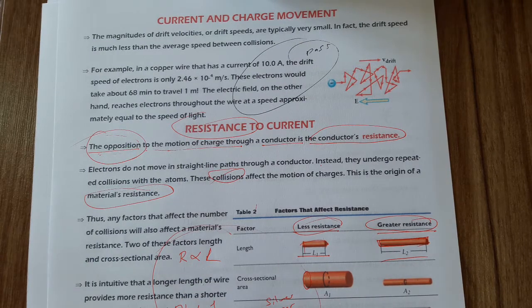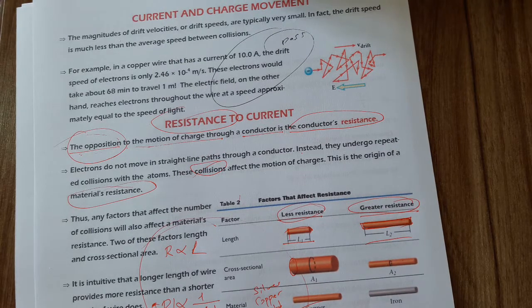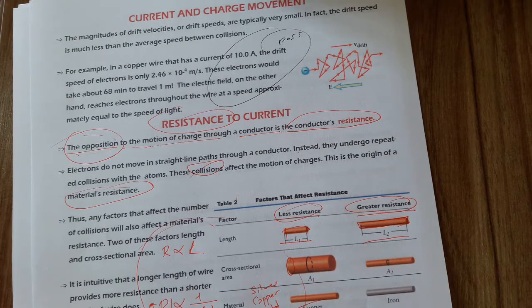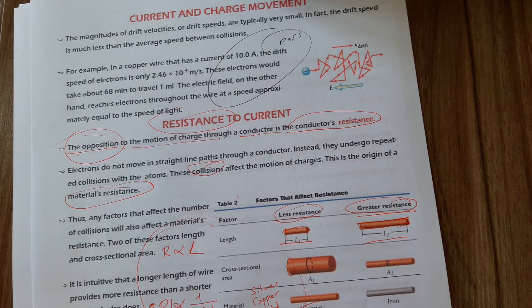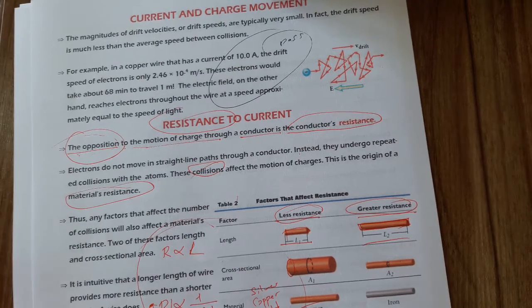So now we know what the resistance of a conductor depends on. It depends on the length, it depends on the area, it depends on the type of the conductor. In fact, there's an equation. This equation is not given in the 11th grade book. This equation is very simple. Resistance is equal to rho times L over A. What is rho? It is called resistivity. It depends on the type of the material. What is L? Length of the conductor. What is A? Cross-section area of the conductor. So these are the factors which determine the resistance.